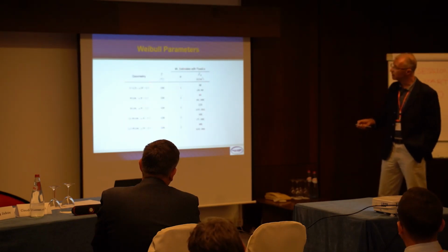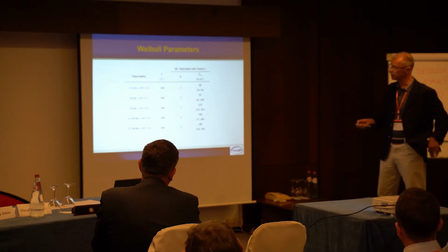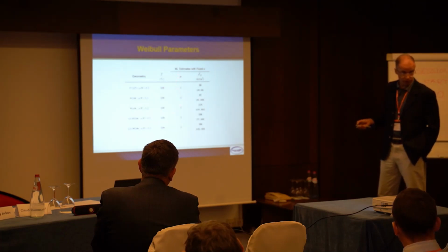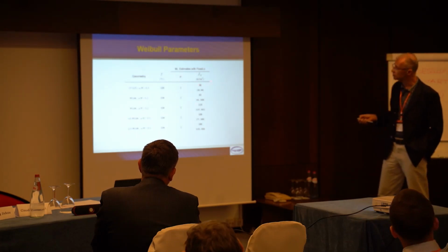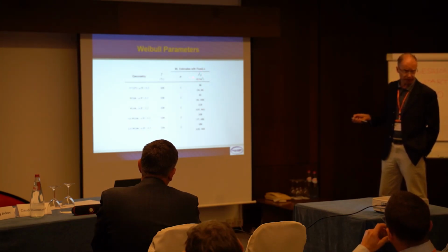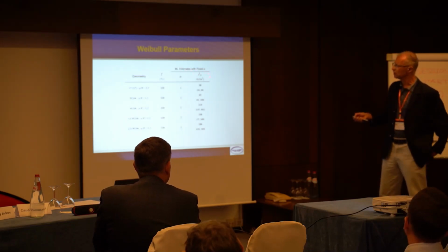Okay, these are the Weibull distributions, not the Weibull stress distribution. The standard Weibull distribution for the toughness data, using a fixed Weibull modulus of 2. I don't have time to go into detail, but there is a mechanistic reason for enforcing a fixed Weibull modulus. This is related to HRR stress fields and other things that we don't have time to discuss. This is the key parameter here, called the characteristic toughness. It's very close to the average. Okay, it's not quite the average.